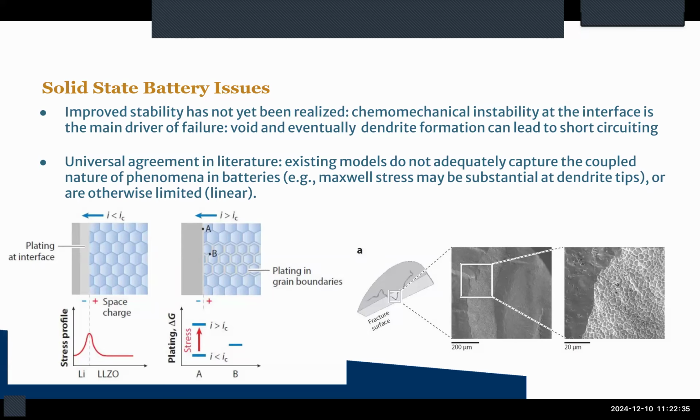right. And moreover, something you'll notice, this is a nonlinear theory that we're developing and trying to implement. That's really important because it's been proven that even in small deformation cases, the shear strains in particular that end up leading to failure cannot be properly modeled in a linear theory. It's been shown that you get upwards of 2 to 3 times the shear stress just by accounting for nonlinearities in the deformation. Should almost be expected because of the amount that these batteries swell: silicon swells 300%, but lithium swells about 5%, and even that's exceeding the range of the linear assumption. So we need to solve this instability issue.